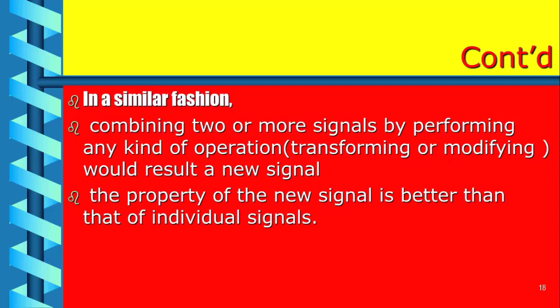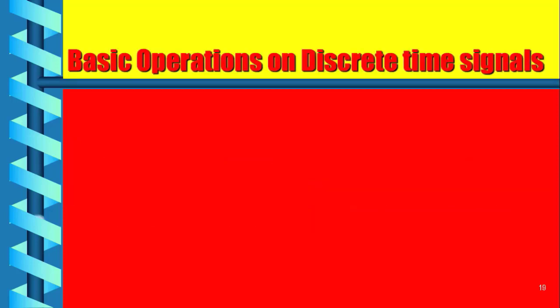Now, let's take one example. Audio signals are used for very short distance communication. When you are speaking, someone across the room can hear you. On the other hand, radio frequencies are very good at propagating over long distances. For instance, if a 100 volts 1 megahertz sine wave is fed into an antenna, the resulting radio wave can be detected in the next room or in the next country. That means modulation is a process of merging signals to form a third signal with desirable characteristics of both.